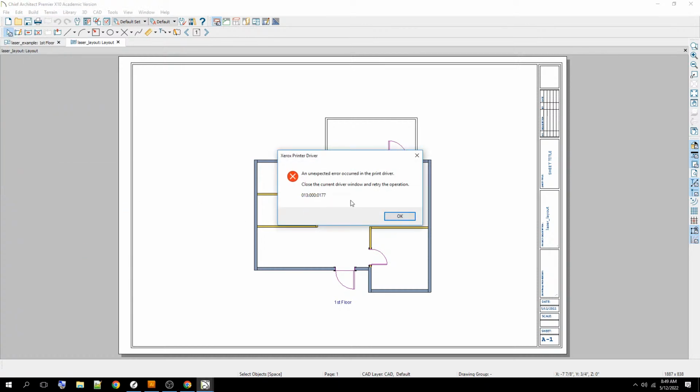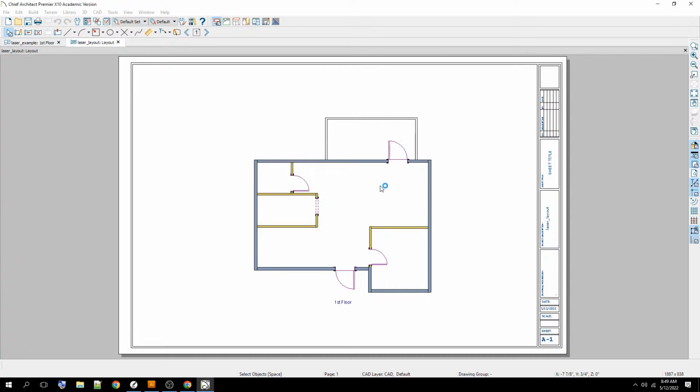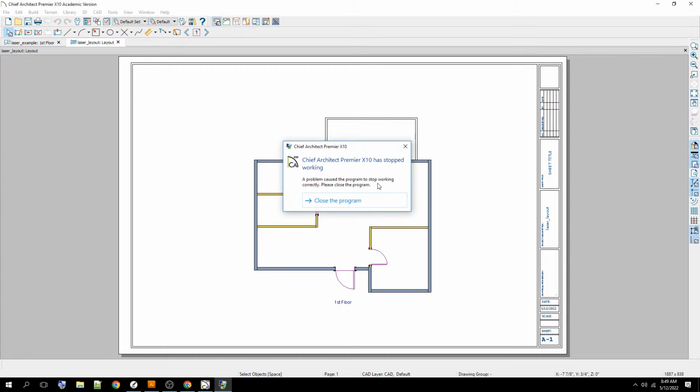And as long as my computer doesn't crash, which it looks like it's going to, you will normally get your printer options. I have no idea why it's not working, other than I'm trying to record this video. When you look at your printer options, you'll see all the different physical printers, but one of them will say PDF. Choose the PDF, and when you say OK, if it asks you for the scale, you're going to leave it as a 1-to-1 scale. Whatever this document is in size, you need it that size because you've already made your scale. If you scale a scale, you're going to be off and it's never going to work, right?